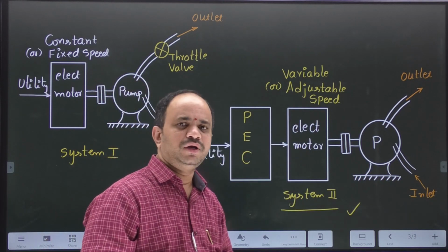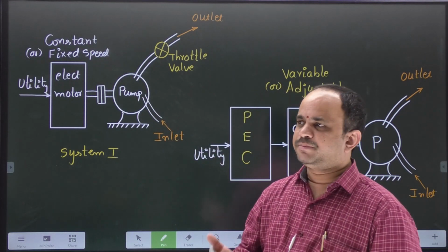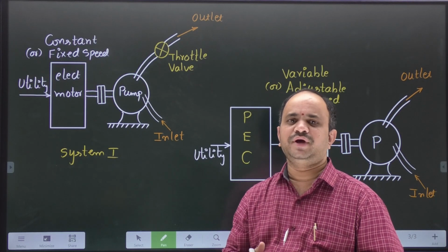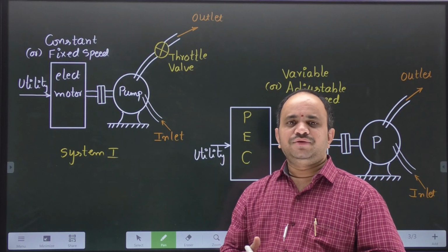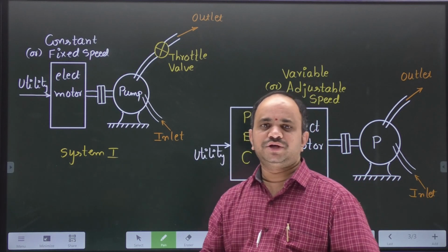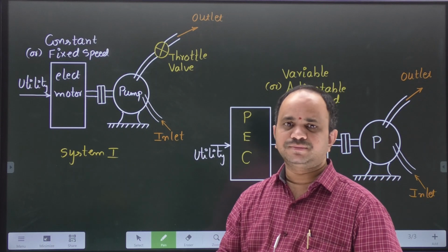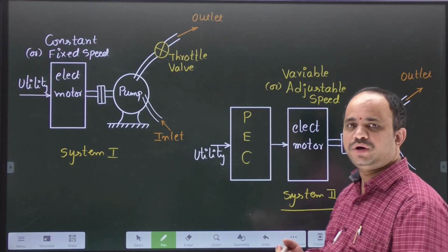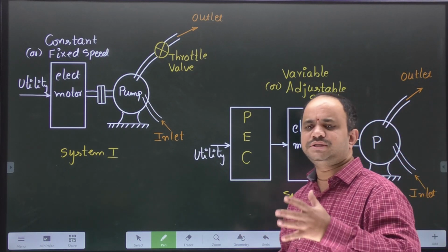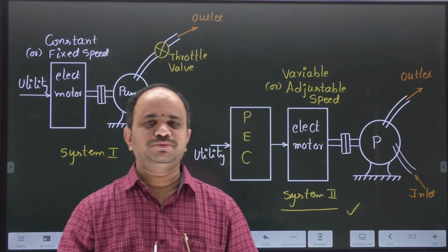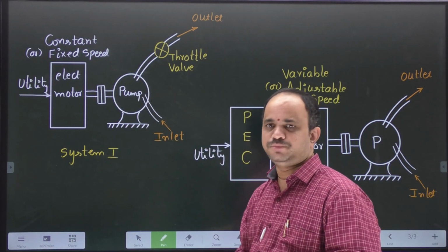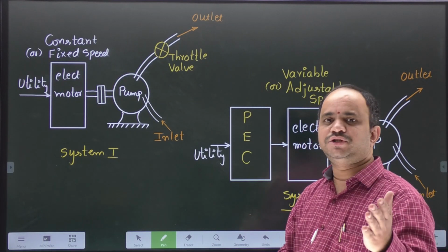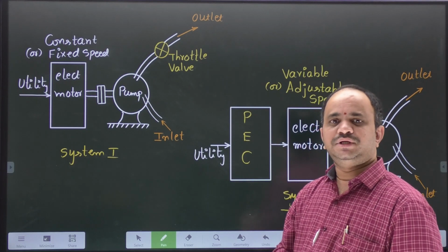Basically, we will have rectifier systems. If the supply is a single phase AC, we will use single phase rectifier circuits, of course phase control rectifiers. And if the supply is three phase, when you go for higher power applications, we will use three phase rectifier circuits. And if the supply is a DC supply, unregulated DC, then you will have chopper circuits. All of these various power electronic circuits were explained in detail in our previous modules. If you have not gone through those modules, I highly suggest you first finish those modules and only then come to this drives topic.